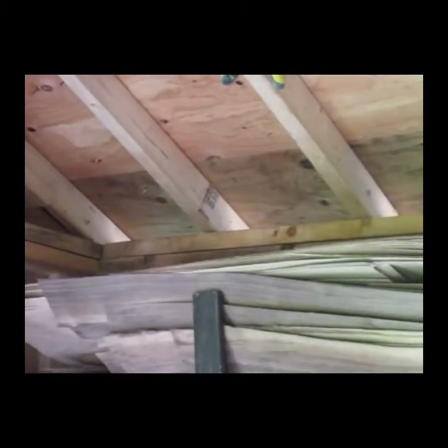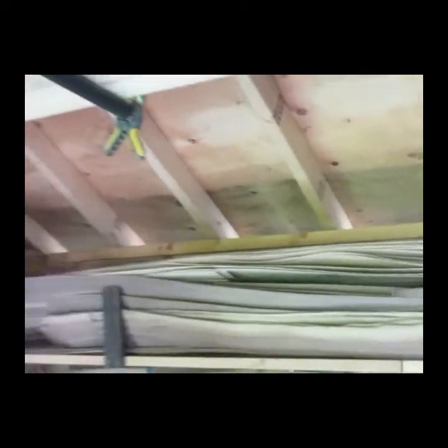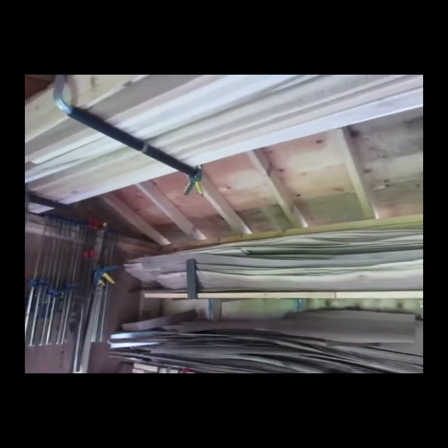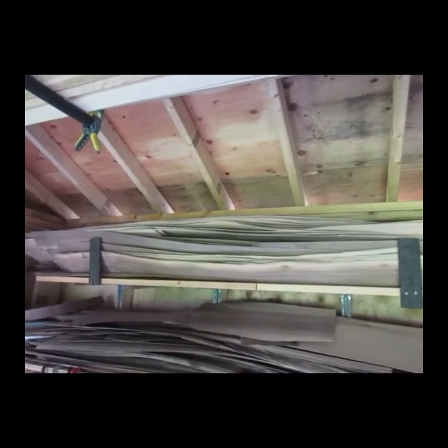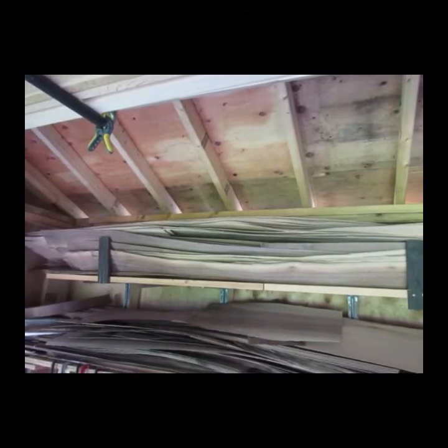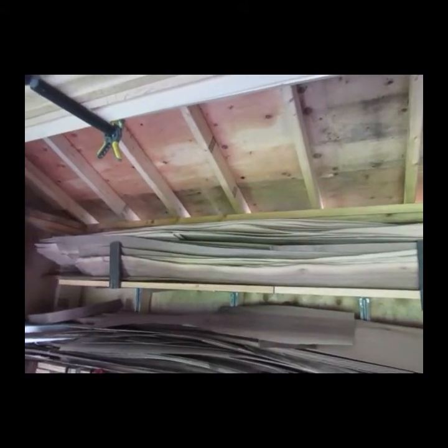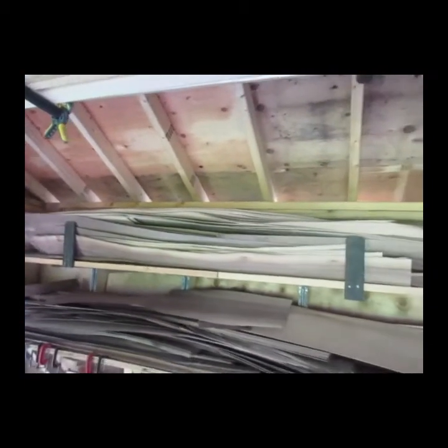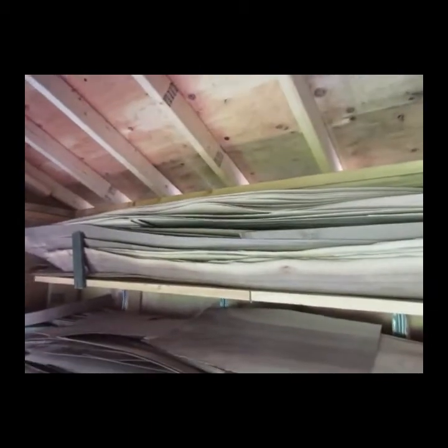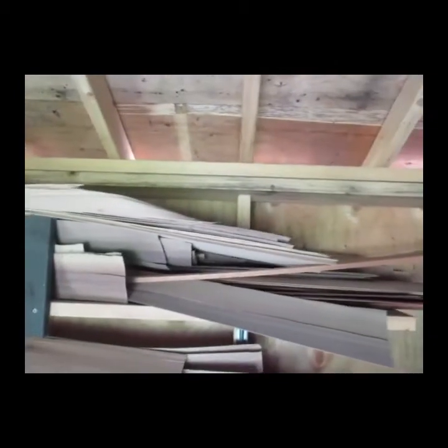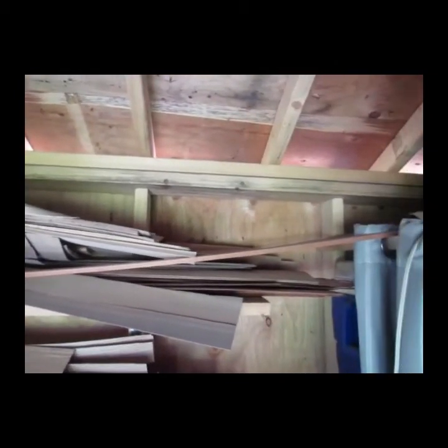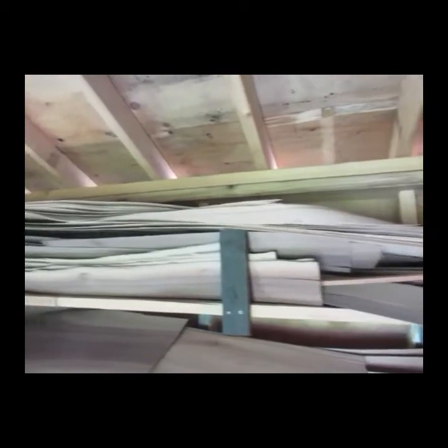So what we've got is 2x4s that rest on top of the wall, as you can see. They just rest on top of the wall and they're toe-nailed in place. Now a different fastening technique is called a bird's mouth. Take a look to the right of your screen, and you'll see a notation in this Edpuzzle that shows you what a bird's mouth is and how to perform it, how to make sure that piece of wood rests on top of the wall. That truss rafter, as they're called when you stick frame, rests on top of the wall using a bird's mouth.